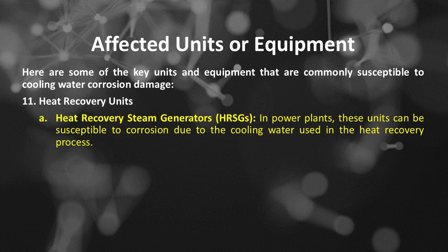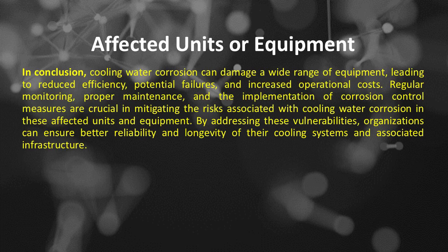These units can be susceptible to corrosion due to the cooling water used in the heat recovery process. In conclusion, cooling water corrosion can damage a wide range of equipment, leading to reduced efficiency, potential failures, and increased operational costs. Regular monitoring, proper maintenance, and the implementation of corrosion control measures are crucial in mitigating the risks associated with cooling water corrosion in these affected units and equipment. By addressing these vulnerabilities, organizations can ensure better reliability and longevity of their cooling systems and associated infrastructure.